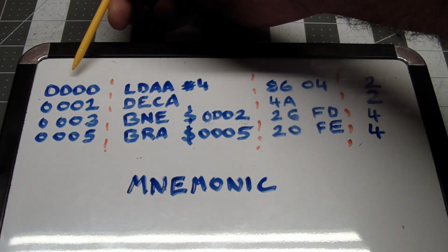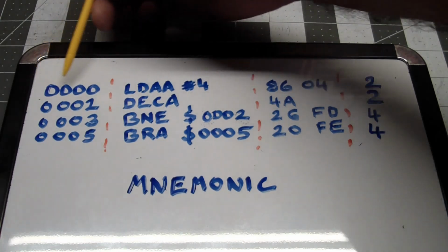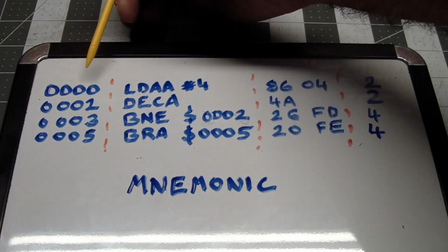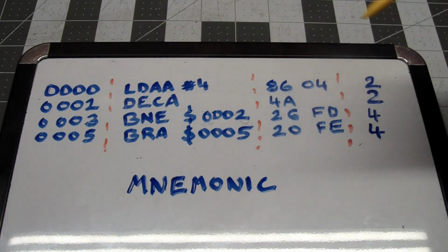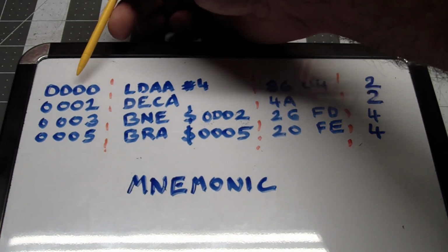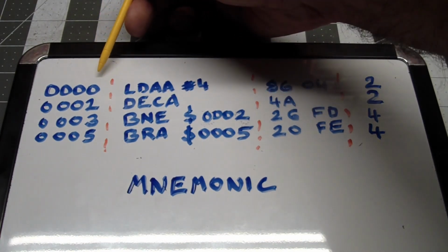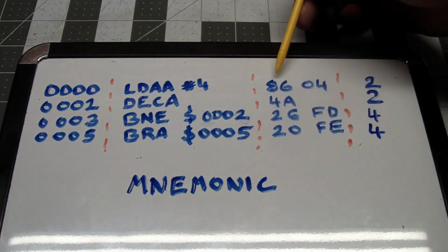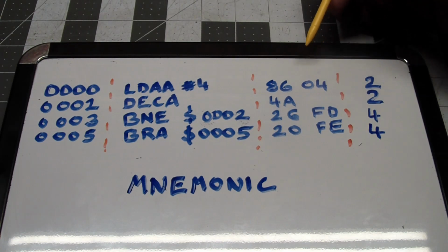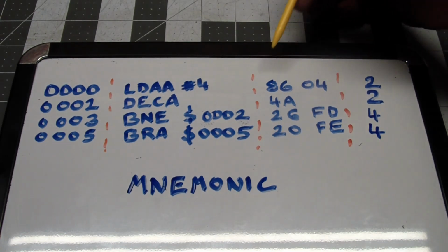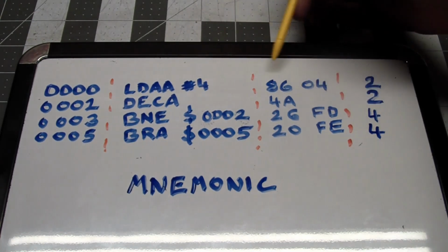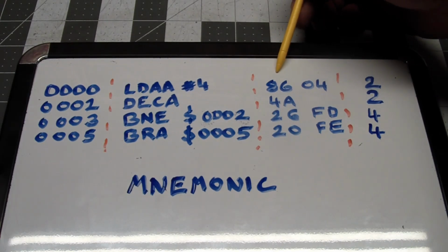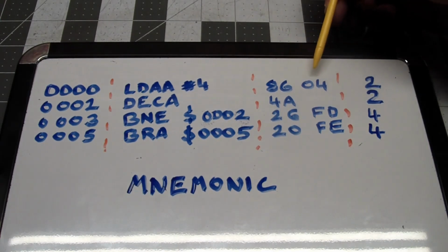When a program is executing, the program counter will be set to an address. And in order to start this program, we have to set the program counter to 0. When it runs, it knows to fetch the next instruction. And during the fetch, it also knows how many bytes to fetch. It will fetch the first byte, and it will internally decode it and immediately know that there's one more byte for it to fetch.